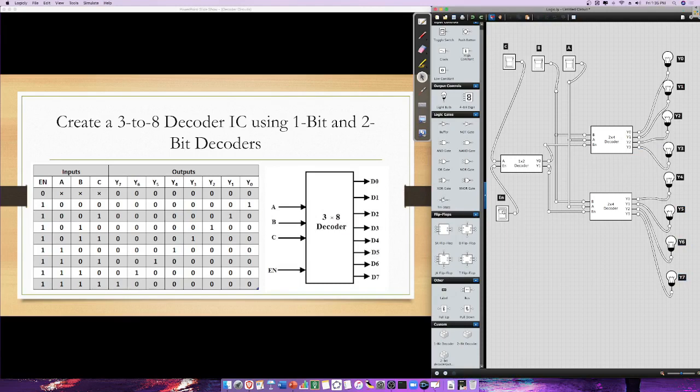Let's enable the IC. So when the 1x2 decoder is enabled, meaning to say this letter C will select Y0. Y0 is selected and then it enables the 2x4 decoder. So this 2x4 decoder now will be enabled and it will display Y0 because of the combination of A and B, which are zeros. Okay, so that's how you explain it.